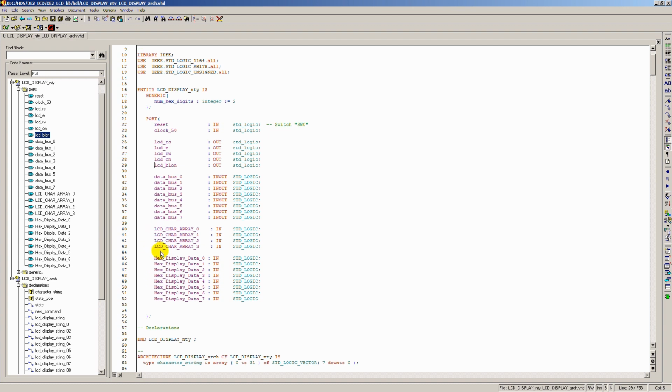These 4 input pins are assigned to a series of switches, and based on their logic high and logic low levels, that will dictate a state machine to display a specific message on the screen. Then you have these 8 switches, which are actually part of the existing core, and they control 2 separate specific characters to be displayed, of a certain value based on their logic condition.